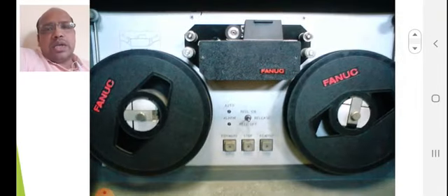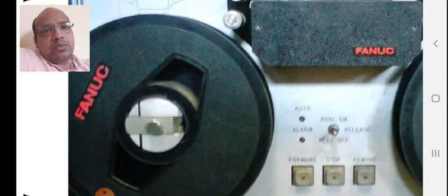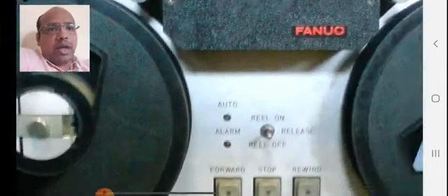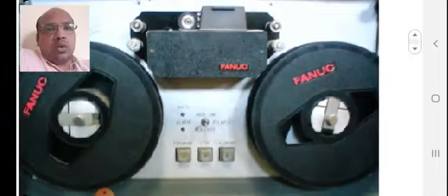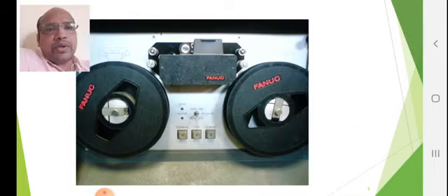It is just like old days we were using tape recorders. These are the rollers, and over these rollers punch tape is mounted, and when these rollers roll, then punch tape is read by a machine control unit, and accordingly it performs the operations. So in this photo, Fanuc is shown, FANUC. This Fanuc is a name of a controller, and this right one and the left one both are the rollers over which punch tape is mounted. Therefore it is called a punch tape reader.